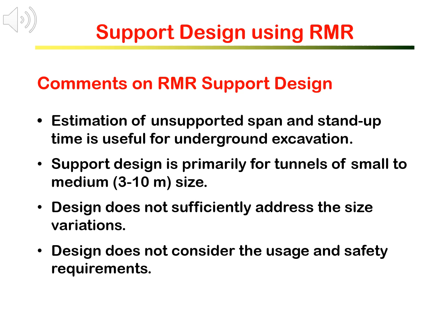The design is primarily for tunnels of small to medium size, mostly below 10 meter diameter. The design does not sufficiently address the size variation. The support requirements are rock mass quality dependent, but not size dependent.